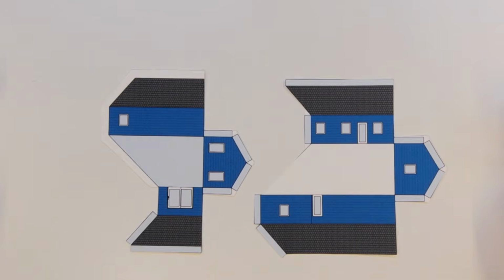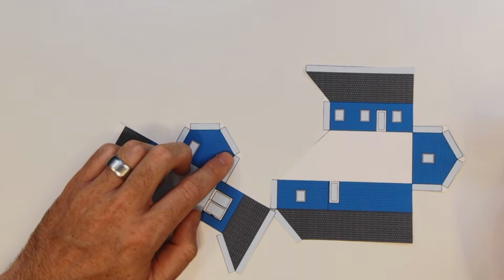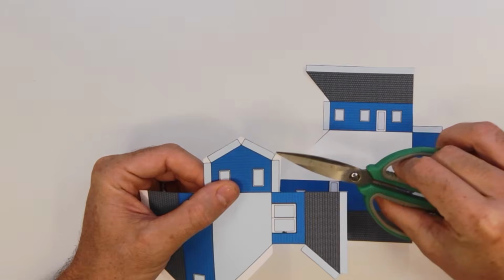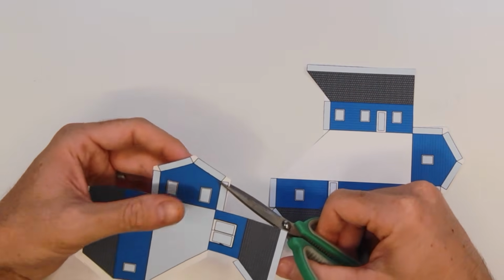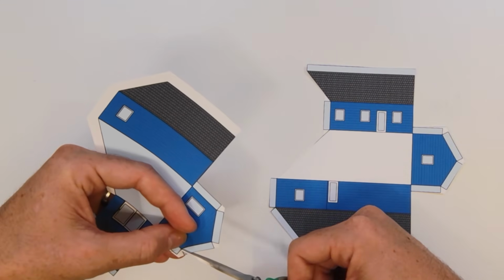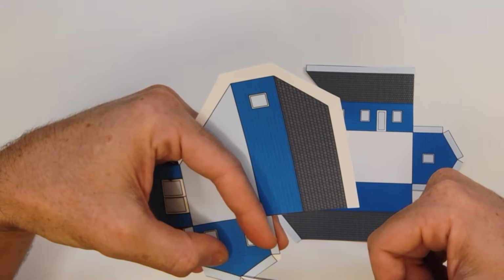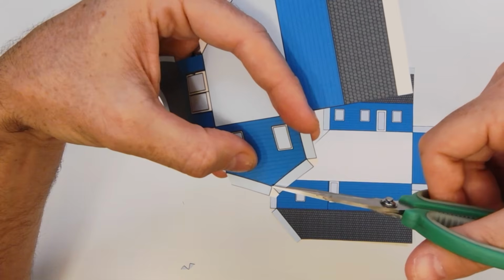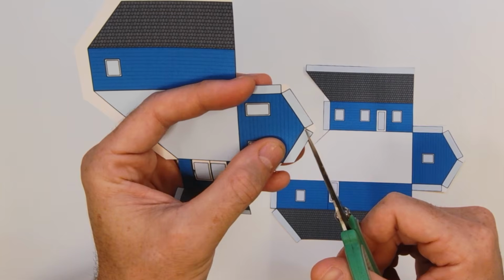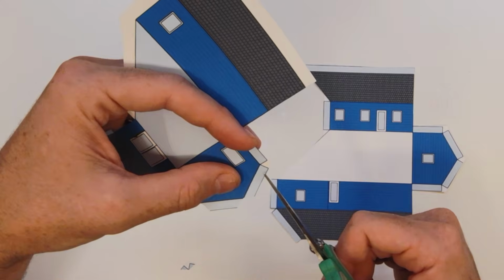Now that we have our two pieces cut away, let's go in and focus on some of the tabs and see how we can clean those up. I didn't do a particularly good job cutting some of the edge here. So I'm going to go back through, and one little tip that actually helps when adjoining these is mitering the tabs themselves. If you look here, this is a straight cut. What I'll do is I'll come in at a 45-degree angle to that cut. And I'll do the same thing over here. Come in at 45 and just cut that tab off. That's going to make it easier to transition and fold and seam the next two pieces.